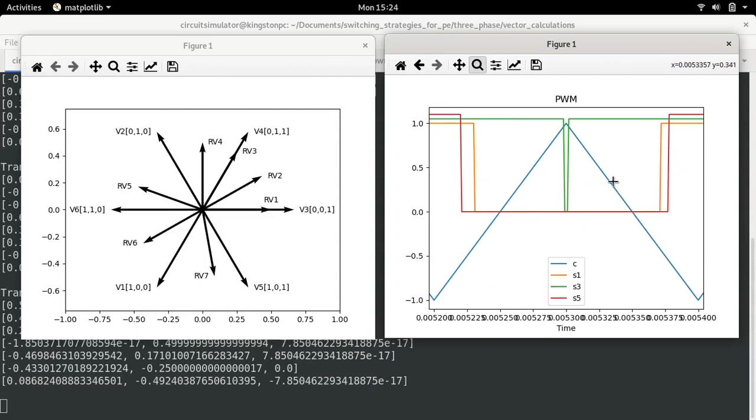Only then can we guarantee that we have pulse width modulation, and that pulse width modulation is what we need to ensure that the Fourier analysis or the frequency analysis of the output voltage waveform of the converter will have high frequency components in the carrier frequency range, which can be filtered out conveniently. This is important. If we have some other strategy which is non-ideal, we can't guarantee. We may end up with some other kind of frequencies, and those frequencies may not be that easy to remove.